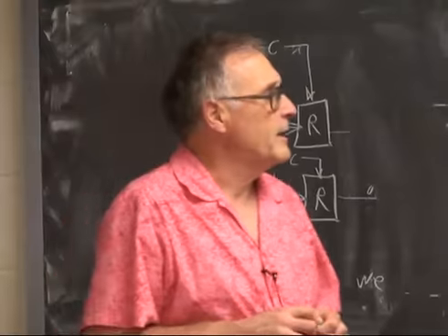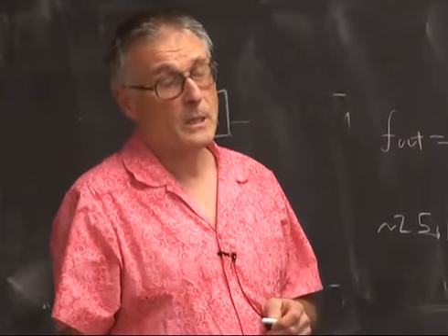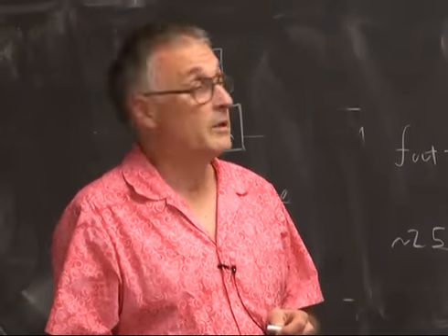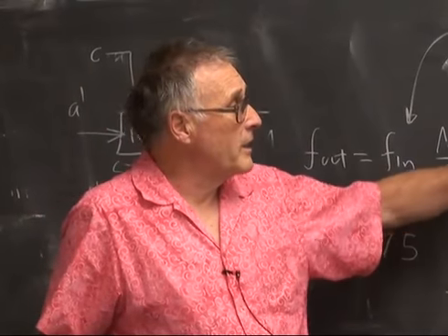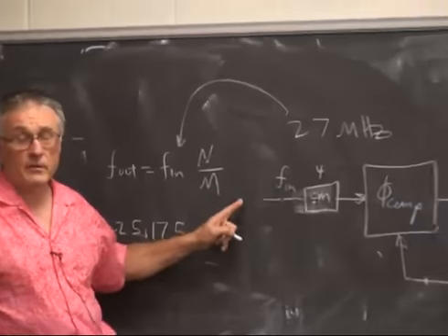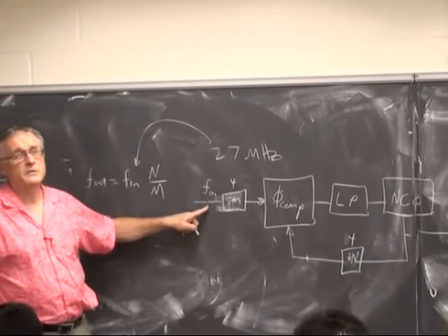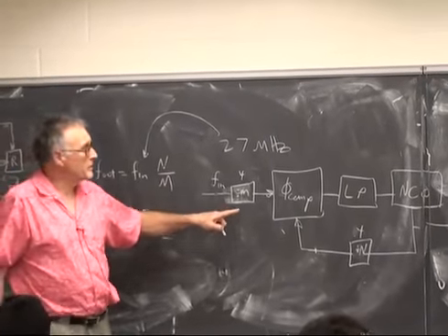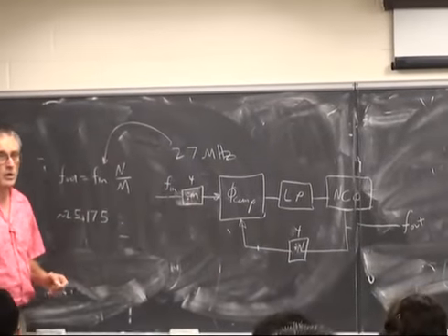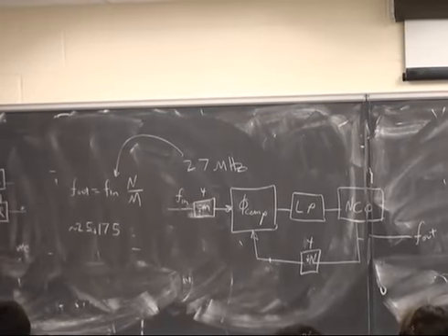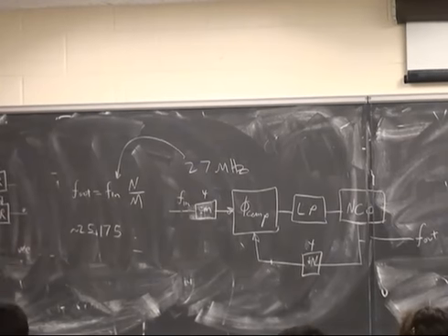So the way that phase lock loops are used on this particular chip, they are used to make one frequency into several other frequencies. I've played with it a little bit. You can take the 50 megahertz signal and you can clock it up above 200 megahertz, and M4K blocks still work. Some other circuitry fails before that, depending on what you build.